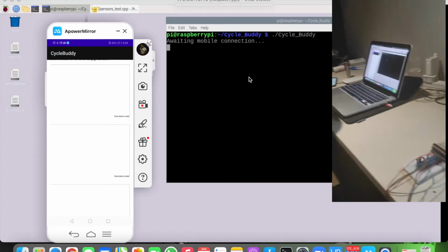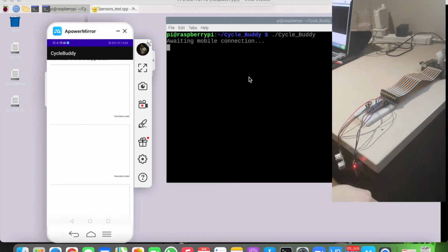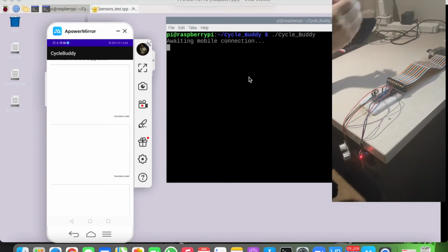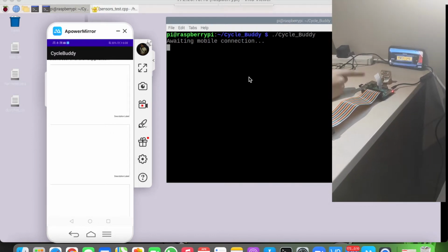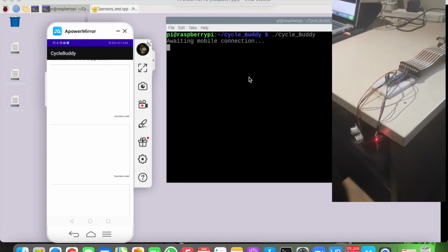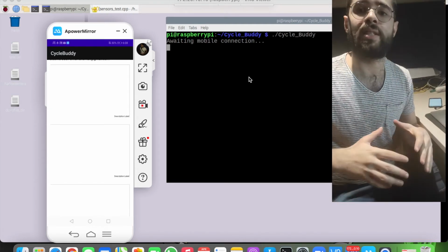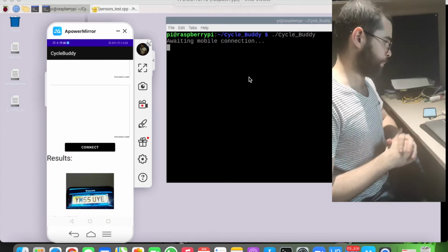This is our system right here. We have the ultrasonic sensor and the Hall effect sensor. I'm going to trigger it by moving my hand and triggering the Hall effect sensor with a magnet. We have a car plate right there in the UK that's going to be captured by the Pi camera once the ultrasonic sensor gives us low distance and high velocity, and the Hall effect sensor is going to give us huge bike velocities. This will trigger the camera to take the picture.